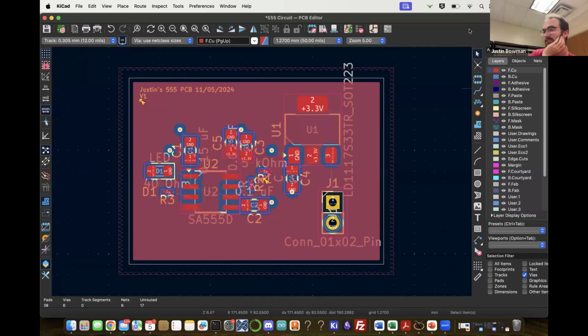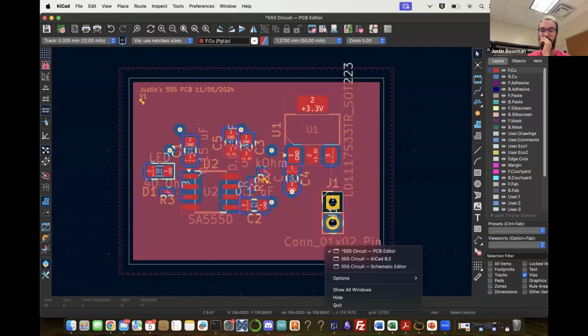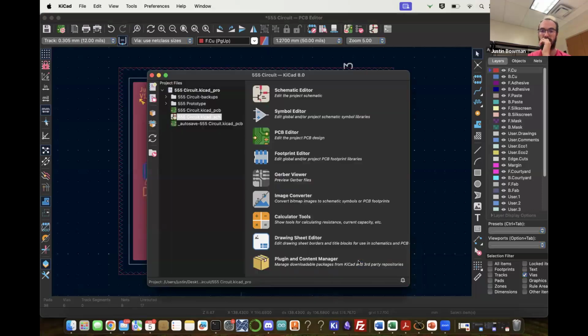The Gerber file is going to have all of the different layers. That is for manufacturing, right? What I'm saying is, you and I are collaborating, let's say, and I want to send you my updated code. What should I email you? If we both were using KiCAD, you'd basically save the project and build the project and send that to me. Because then I'd be able to switch back and forth between the schematic and the actual PCB, and that contains all of the stuff along with it.